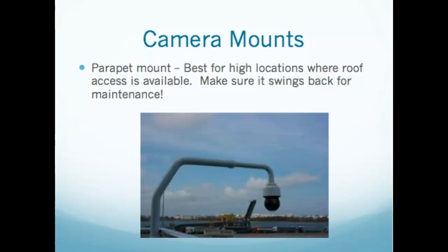And the parapet mount is very cool for one reason, in my opinion. Well, two reasons, actually. It stands off from the building, so you get that same effect you get with a gooseneck, even better because it stands out even farther. And these parapets usually go out about 4 or 5 feet, sometimes a little more. You can extend them, but then they start to look kind of ugly if they get out too far. But when you want to repair the camera, you just swing this around.